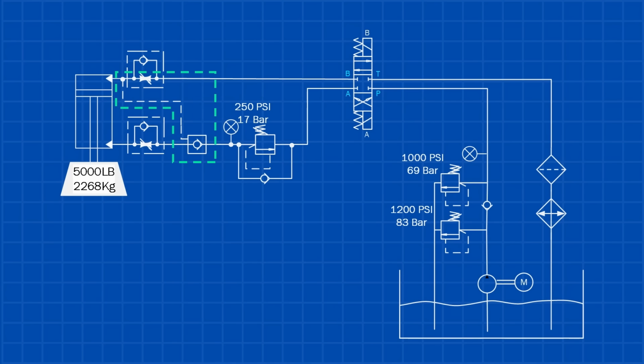With overhung loads, we usually add a pilot-operated or solenoid-operated check valve along with the counterbalance valve for extra safety. This helps keep the load securely locked in place. In our example, when the directional valve is energized for downward movement, the pilot senses pressure at the blind end of the cylinder and opens the check valve. This setup is commonly used in presses. And just a quick tip, pilot lines are always shown as dashed lines in diagrams.